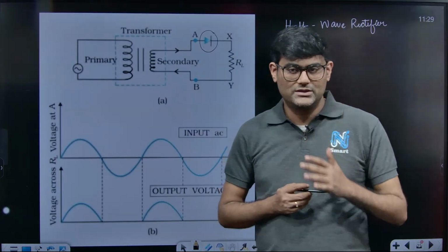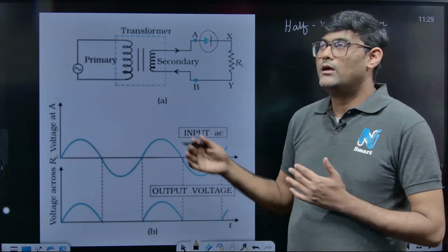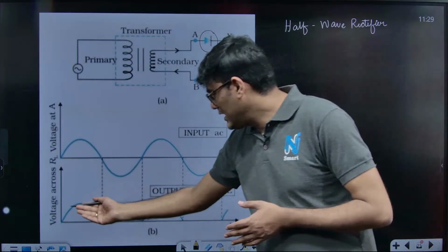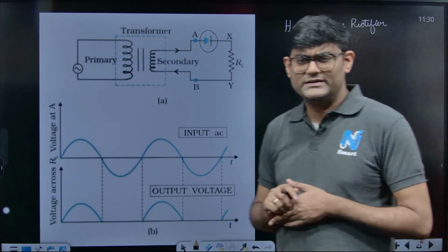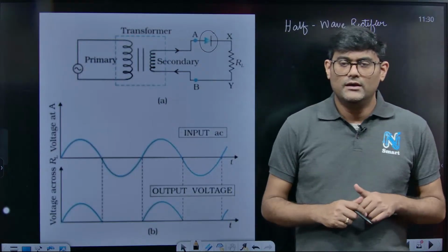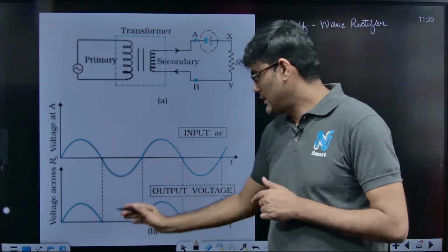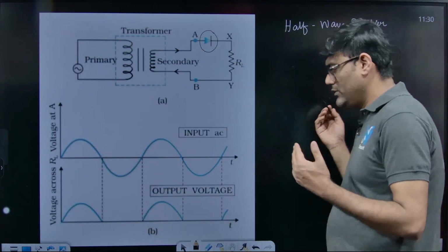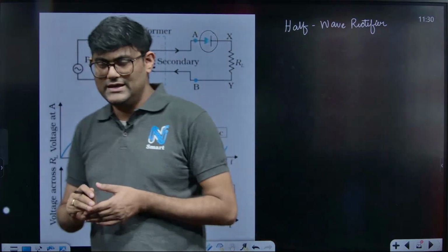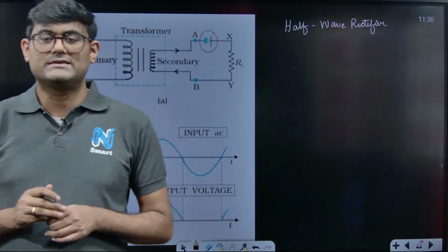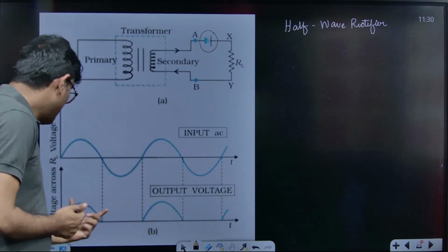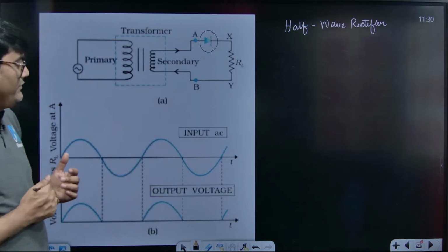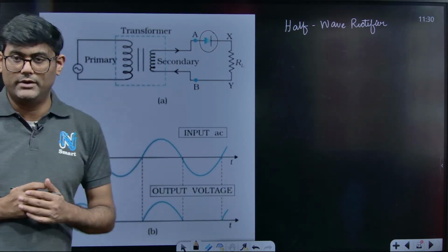They can ask you what is the RMS value of the output voltage that you have got. You can calculate this. It is a part of AC, right? For AC, if you calculate the RMS value, it is I maximum by √2, right? But here the RMS value of a half wave rectifier will not be Im by √2, right?